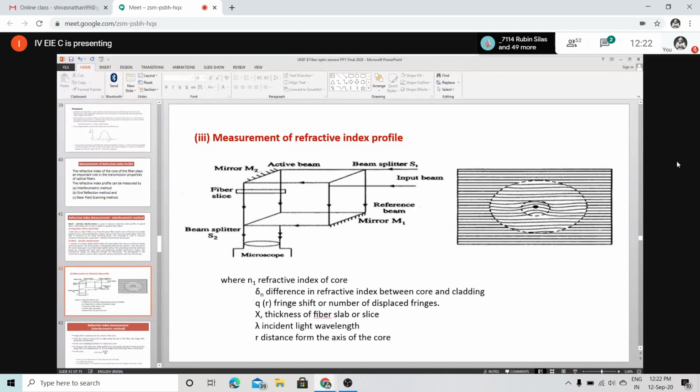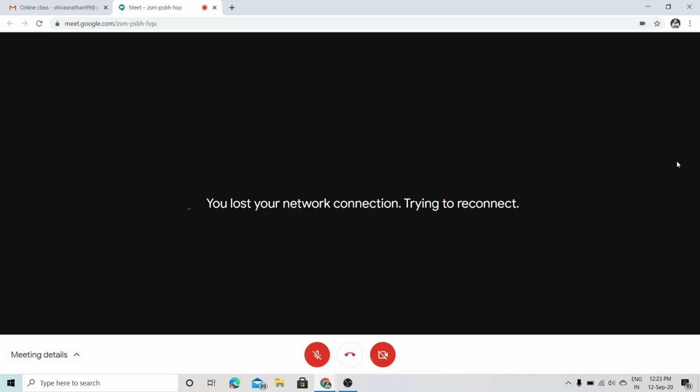So you might come to an understanding that my refractive index pattern inside my core will be more like a Gaussian curve. Exactly at the center of the axis, it will be a dark node that represents the maximum value of the refractive index, and as it moves along, you can find a Gaussian, curvy pattern. And we are speaking about graded index fibers, and you all know that. So the measurement of the refractive index profile is basically designed for the purpose of measuring what? Graded index fibers.